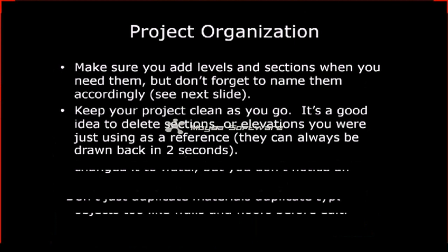And I've seen projects that can go from having 1 or 2 views and then all of a sudden they balloon out of control. One good thing that I'm pointing out is sections and elevations are really helpful to plop in and see about things as you're going. But when you're not using them, they're kind of just in your way. So you either have to hide them or delete them, and a lot of times I just delete them if it's not going to be a final drawing, because that's adding anywhere from 1 to 4 views in a single little button, and now actually 6 if you download the new stuff for Revit.